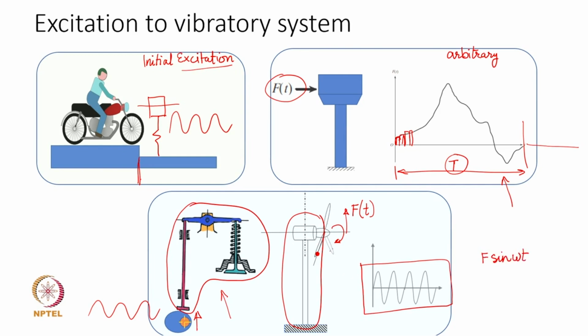So, if this bladed rotor spins at a speed of, let us say, omega radians per second, because we know that the unbalance rotates with the same frequency as the rotation frequency, and therefore, it varies harmonically with the same frequency omega as the rotational frequency. And here F, you all know, is given by m e omega square, the unbalanced force. So, the excitation force F, whose magnitude is this, fluctuates with the frequency of omega, which is the rotational frequency in this particular case.